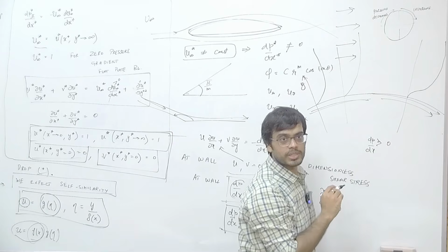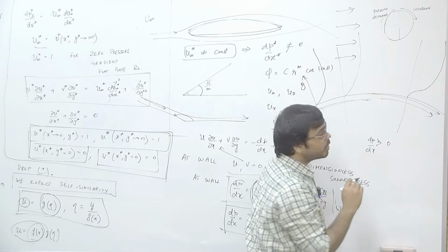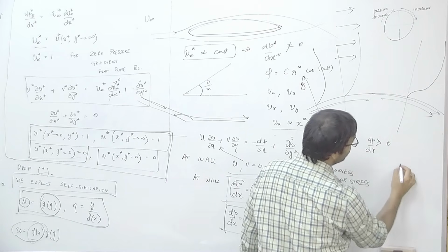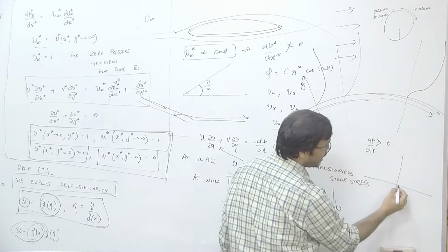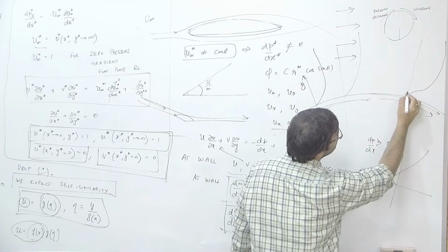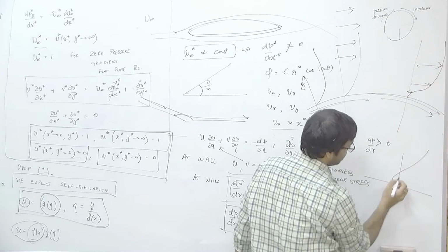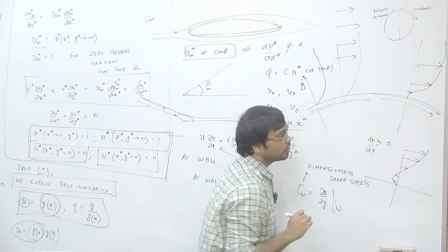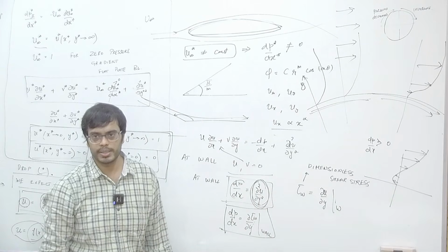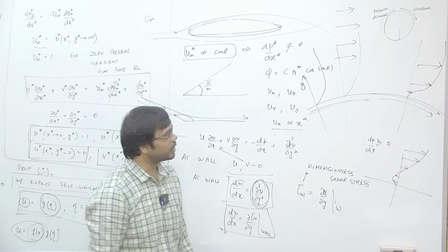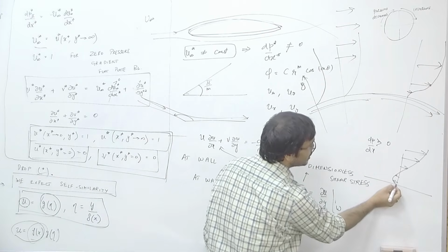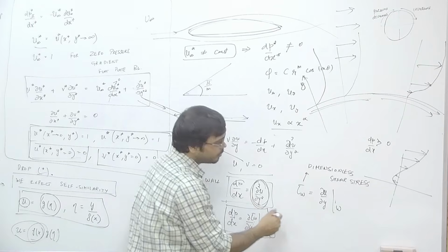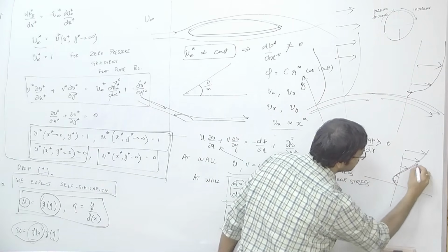If you keep moving further downstream in this kind of a situation, after a certain moment you will see this happening, that your velocity will reverse. Your velocity starts to reverse, okay, because when your del 2 u by del y square becomes very highly positive, this is exactly how it behaves.